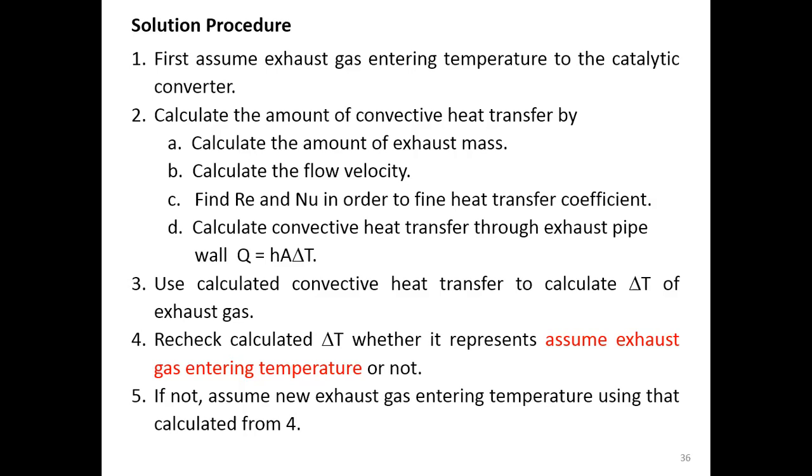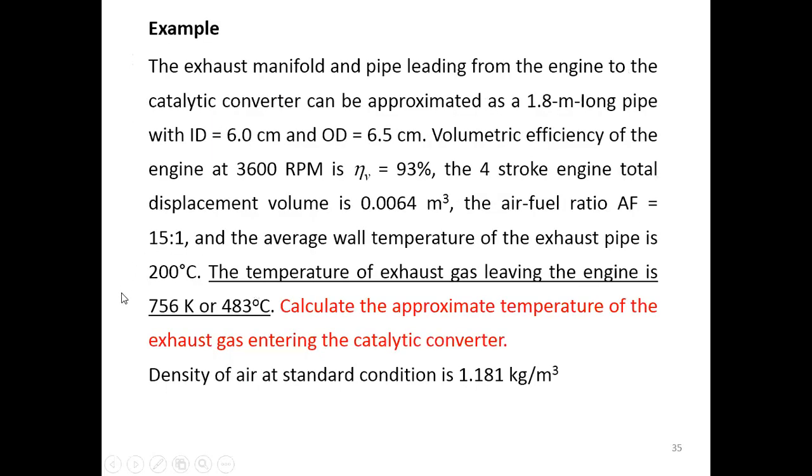So the first step is to assume what they are looking for, the exhaust gas entering temperature to the catalytic converter. How can we assume? We have to make use of the information they gave. The maximum temperature is 483. The minimum temperature of the exhaust gas before entering the catalytic converter has to be 200 degrees Celsius.